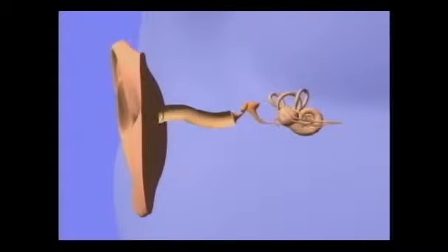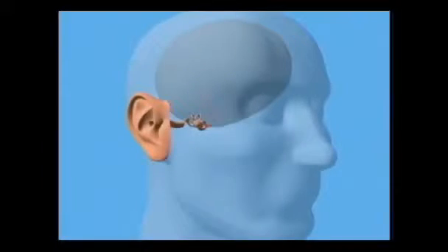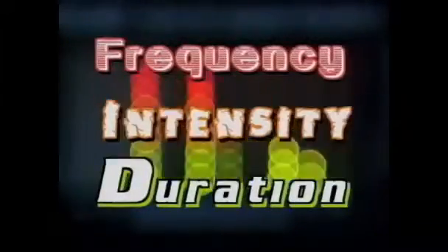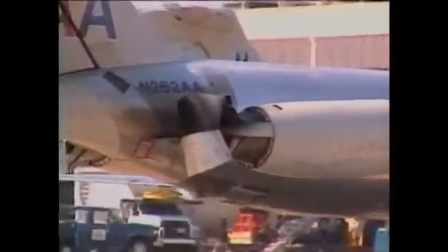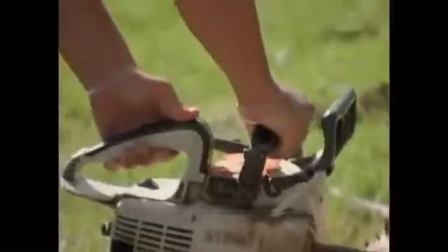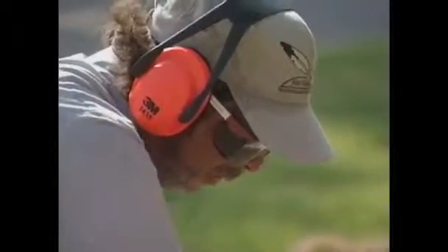In review, hearing is second only to vision as a sensory mechanism to obtain critical information in aircraft operations. The term sound is defined as energy that is heard resulting from stimulation of the auditory nerve. All sounds have three distinct variables: frequency, intensity, and duration. The term noise refers to any sound that is unwanted or annoying. Daily exposure to noise levels higher than 90 decibels can cause a hearing impairment. If ambient noise levels reach 90 decibels, it is necessary to use hearing protection equipment to prevent hearing loss.